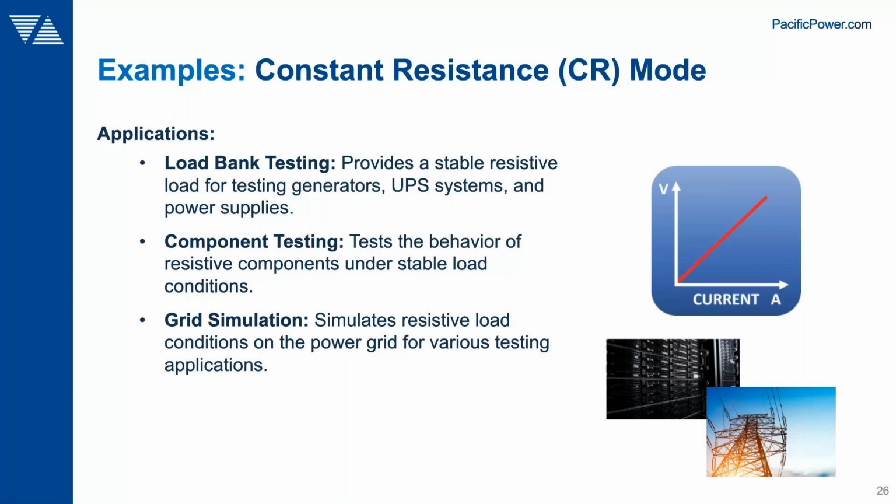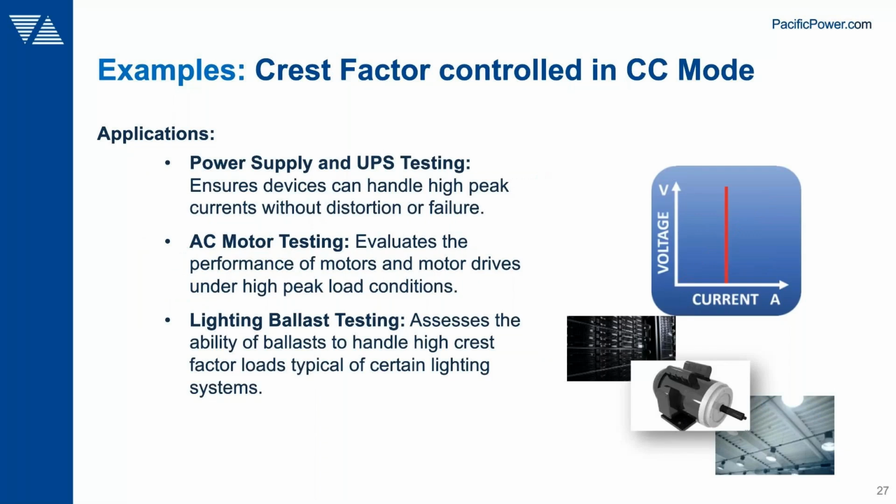Available as well. And we also looked at the crest factor capabilities when we ran the inrush current test, where we had a high crest factor current wave shape or rectified wave shape in this case, and that can be useful for stress testing your products, so your sources. So can they handle high peak currents? What kind of crest factor loads can they handle without excessive voltage distortion, etc. So those are all possible examples of where you would use those kinds of operation modes.